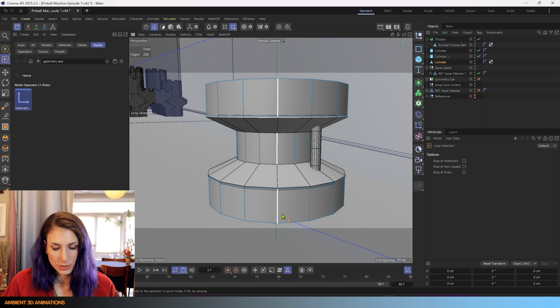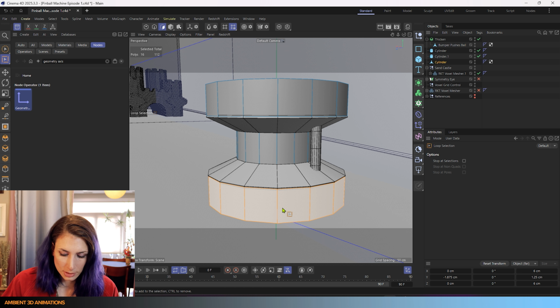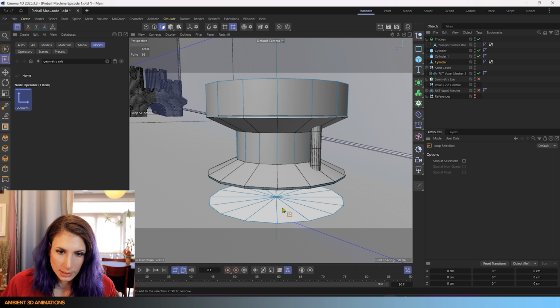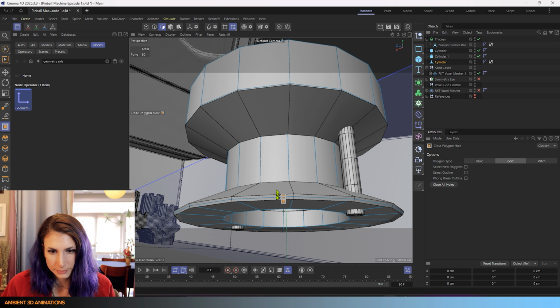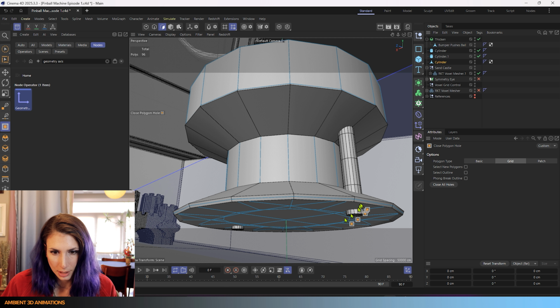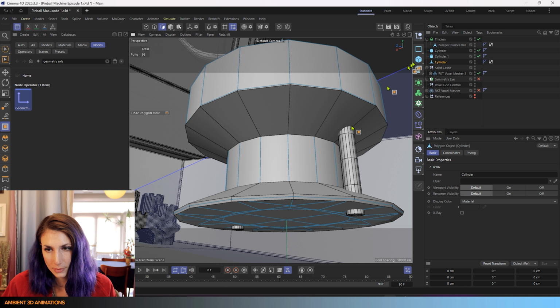This is the cylinder, so I'm going to use UL in polygon mode. I'm going to just go ahead and delete that, delete the bottom, and then I'm going to use MD to fill in this hole in the bottom. And there you go, you can see that that's filled in. And I have grid on, and then I can use UN to select that surface there more easily.